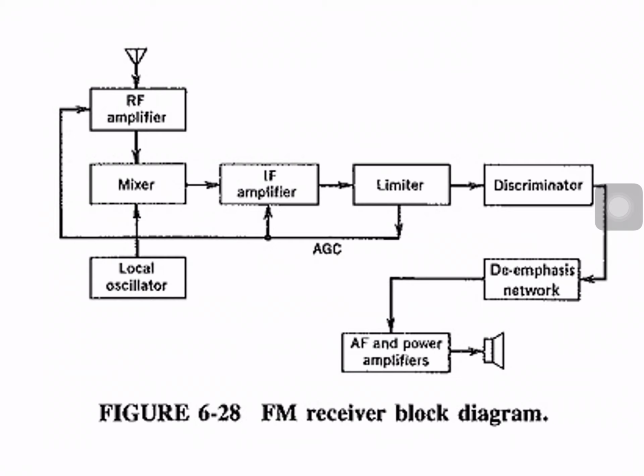The oscillator circuit takes any of the usual forms. The oscillators used here are predominantly Colpitts and Clapp, and these are generally suited for very high frequency operation. Now, tracking is not normally much of a problem in an FM broadcast receiver.